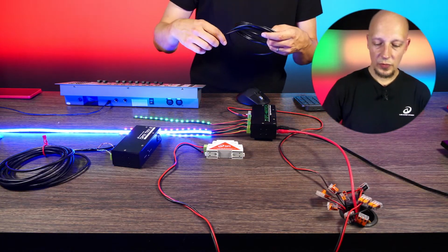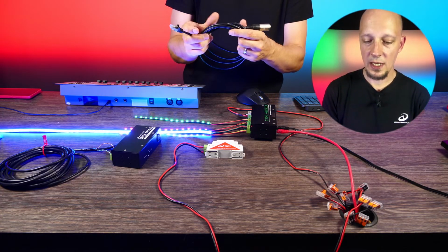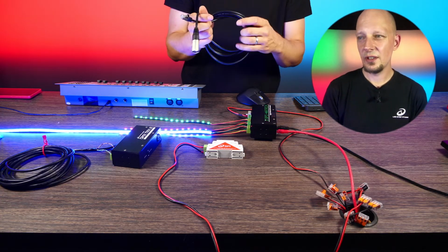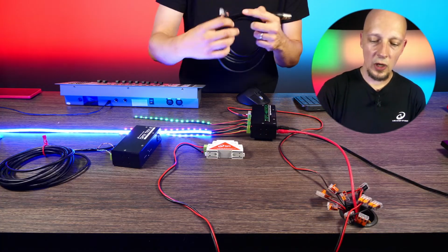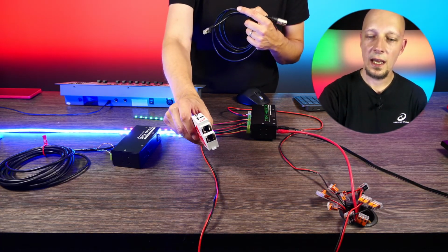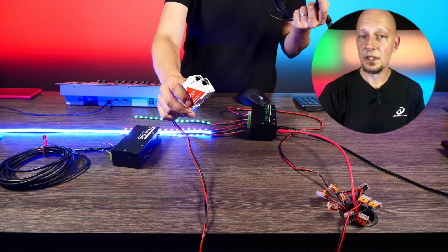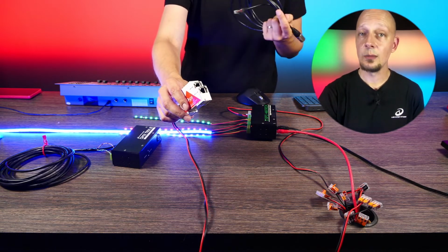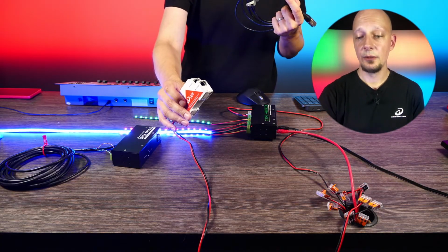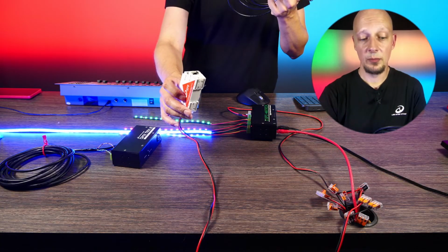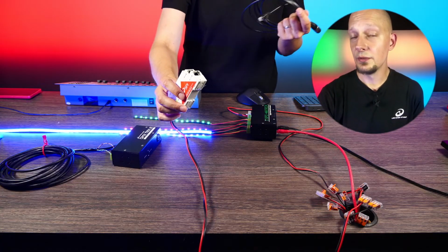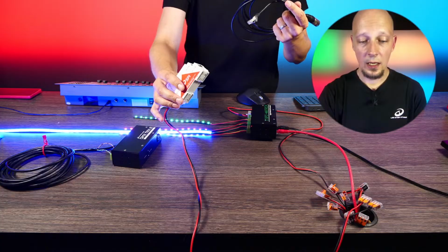I would again refer to some of our previous webinars where I'm talking about this very subject. The cable that you would use to send out the DMX data into your SPI LED controller is slightly different, because on the device itself, for the DMX in and out, we are not using XLR ports, but rather RJ45 ports. The reason is we like to use an Ethernet cable because it's available everywhere, and it's pretty cheap, and its capabilities and performance can be compared to DMX in some instances.